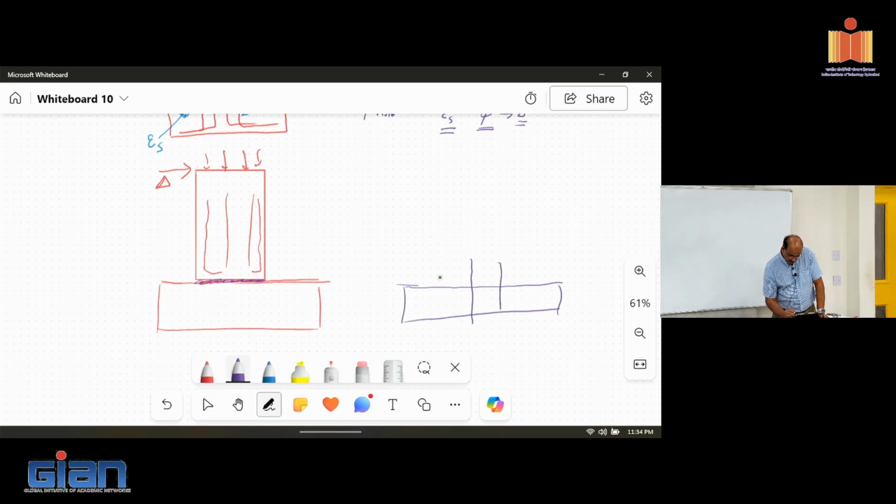Maybe you can evaluate how many rebars you need. This will go into a pocket, but it is not going to be grouted, or it's basically put in a sleeve, so there's no resistance. There's no bonding between the two. So the wall can lift up, but it cannot slide, to avoid the shear failure. That's a good thought.